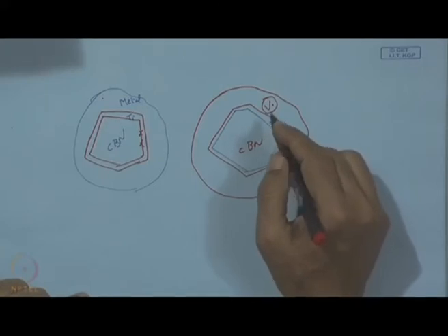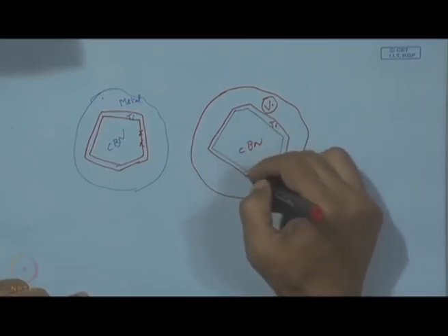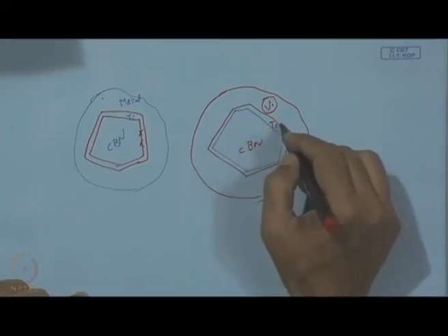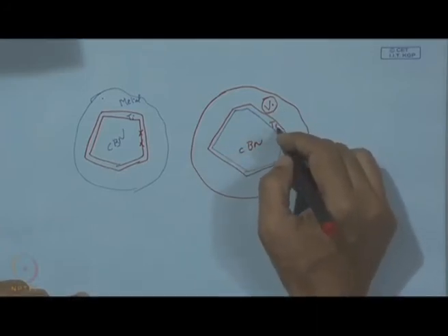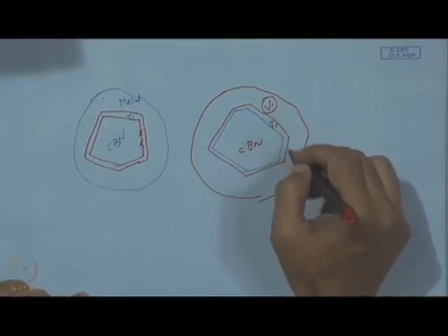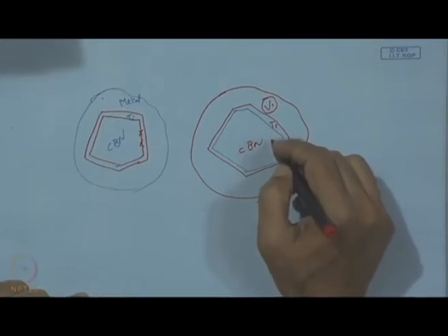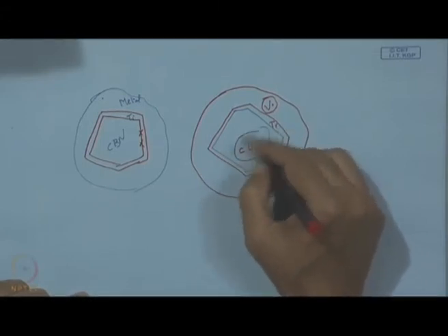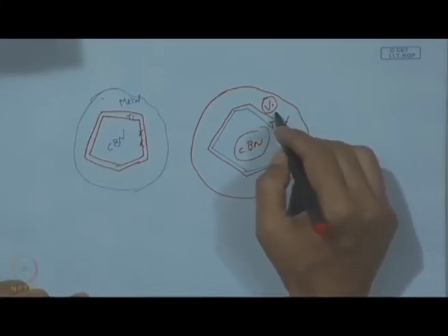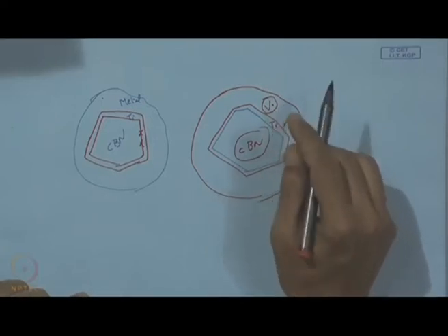So, to prevent that, a coating of titanium is well suited, and the outer side of this titanium during firing can become titanium oxide, and this titanium oxide can fit well with this vitreous bond chemically. This way this CBN grain can also be protected against any possible attack by the vitrified bond at a high firing temperature.